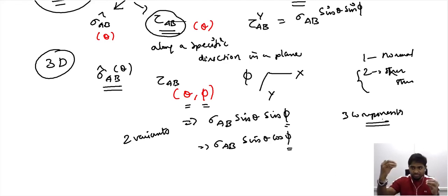You have a uniaxial loading, and this uniaxial loading is inclined, and you have a given region of interest. In that case, what we will be able to identify is one normal component of stress and two shear components of stress. So ultimately, the stress experienced by an inclined plane can be dissociated into three components in a real life condition, or in a given three-dimensional system.